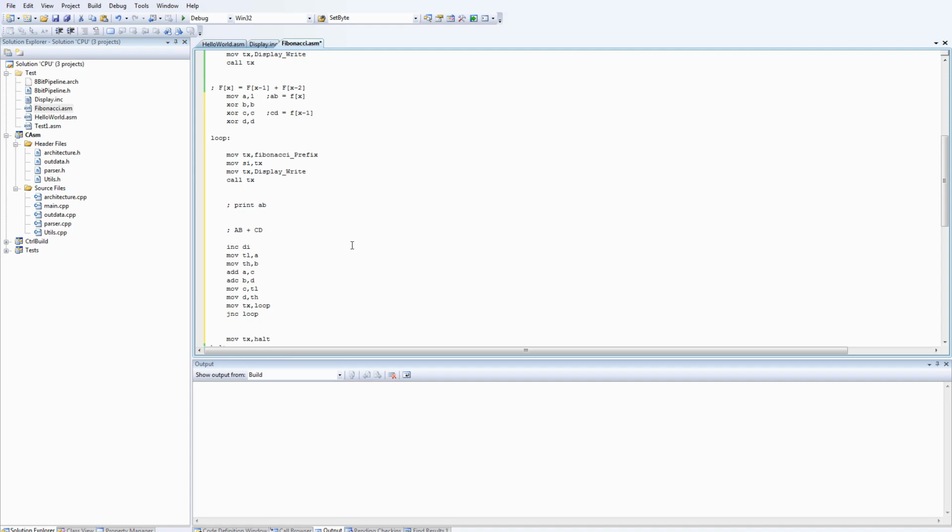If we increment DI with each step, we don't have any spare general purpose registers here without saving them off. We know this function overwrites A. So let's push A. And we want to get the current value of DI, somewhere we can work on it. There should be a lot less than 256 Fibonacci numbers in this range, so we just need to use an 8-bit value.